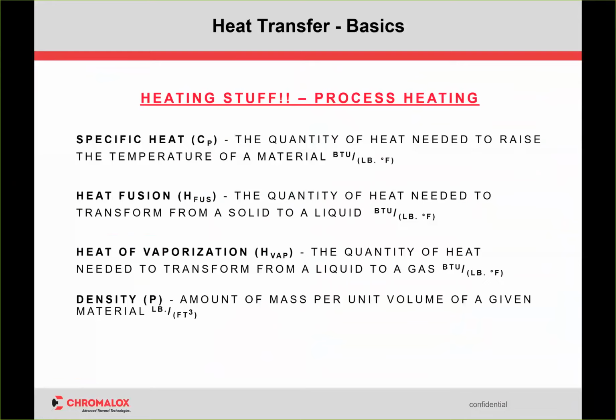A couple of key terms. Specific heat is going to be specific to everything, whether it's the specific heat of the material you're heating, the metal, the tank itself, or the fluid. Heat of fusion is simply, again, you may notice they're all BTUs, and that correlates into kW. Heat of fusion would be the input required when you're heating a solid to a liquid, when you're melting something down. You often think of that as the melting input.